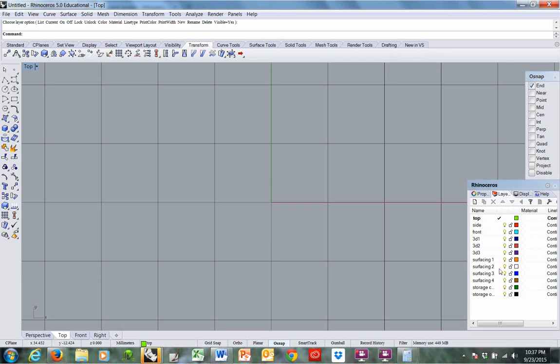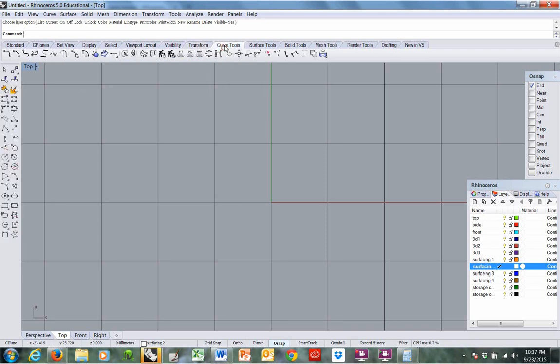Alright, so I'm going to draw a 10mm round brilliant stone. To begin, we'll start with a circle, center, radius. Center of circle is 0, enter. And we want to make sure it says diameter. We do not want radius, we want diameter. Type in 10 for 10mm, hit enter.